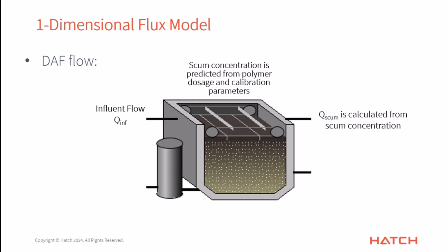And then from that, and some of the other parameters on the menu, we calculate what the flow rate is going to be as it comes off. So we now have a concentration and a flow. And since we know this flow and we know this flow, we can calculate this flow down here. We are basically saying that whatever isn't taken off here, the rest of it is taken off at the concentration of the lowest layer down there. And then of course you've got your layers in here. So now this is a completely nice mass balance all the way around. Okay, so that tells us how we're going to operate this model.